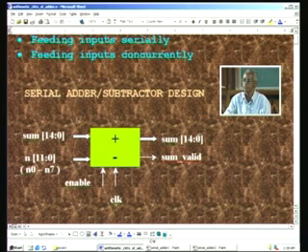This is what is implemented in a serial adder. In contrast to this, we have the parallel adder, in which case we can apply all the 8 inputs at a time, at one stroke, and of course with reference to a positive edge of the clock. These are the 2 things that we have seen. That is, serial adder is one possibility, another is concurrent or parallel adder, and if you want very high speed processing, naturally you go in for this concurrent adder. Where chip area is of great concern, we go for a serial adder. And let us have a look at this serial adder.